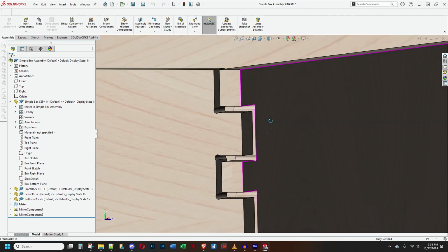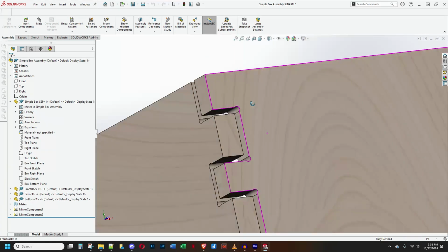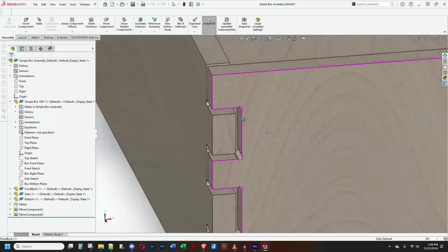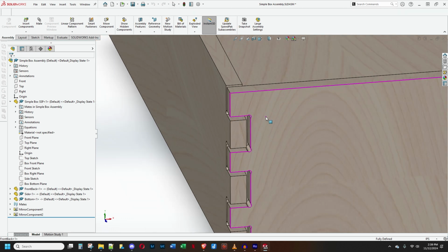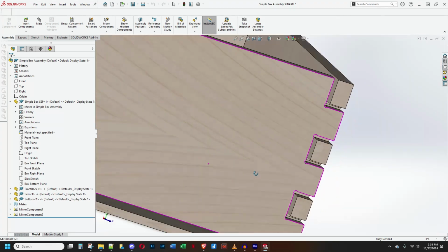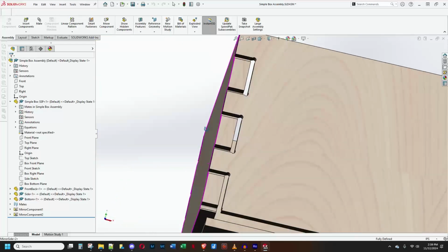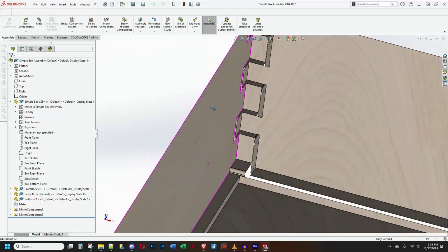Now look. Have I got that tolerance? There are several problems that could happen when you're applying the tolerance. One of them, oops, you forgot. It's not there. When you were building the model, you didn't realize that there was an edge that needed a tolerance, so you didn't put it on there. Another common mistake is to apply the tolerance to both sides, both parts, so the gap would be twice as big as it should be. That's another one. And there's a third one that slips my mind for a second.